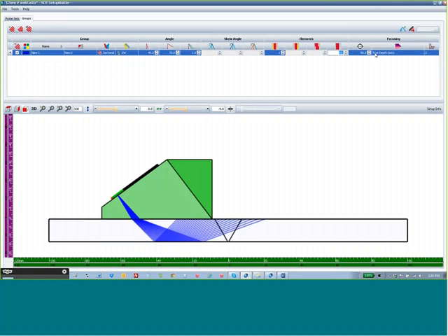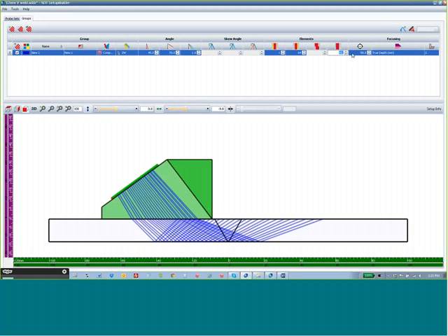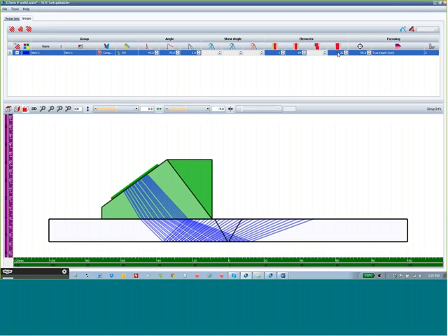I had said our first decision is to select the appropriate aperture for the weld bevel thickness or sound path, and we're going to change our traditional S-scan to a compound S-scan. With selection of the compound S-scan, we can now define the front position, and we'll use the entire probe for the first element, and the last element position of 64 here. We'll reset our aperture to 24.